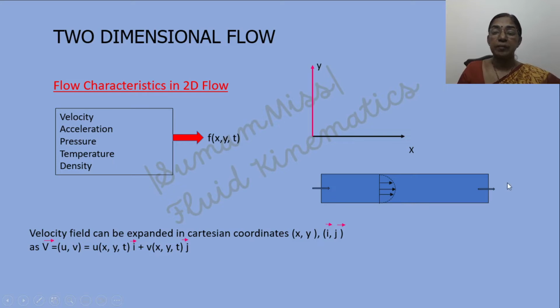Consider the flow through a pipe. The pipe is running full and the pipe is horizontal. If you are considering the variation of velocity along the length of the pipe and across the section, then if you plot the velocity profile, it will follow the shape of a parabola. That means the velocity is 0 at the boundary and it will be maximum at the center of the pipe, which more or less represents the true nature of the flow characteristics.